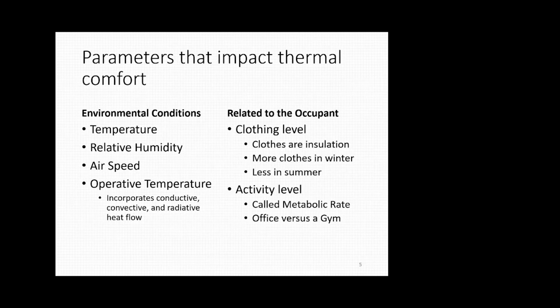If you're talking about BTUs, 1 BTU is about the equivalent of a match or a candle. If you're burning a candle, that's putting off about 1 BTU of energy. It takes 1 BTU to raise 1 pound of water 1 degree Fahrenheit. So when you think about changing phase of water, it takes about 1,000 BTUs, a lot more, to evaporate 1 pound of water. That's just something to think about to put that into perspective.